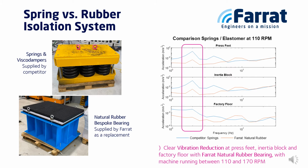Based on this recommendation, the factory went for spring elements and visco dampers as shown in the photo, supplied by one of our competitors. It was reported that the surrounding buildings stopped perceiving vibrations generated by the machine after installation of the product. However, at the same time, it was also observed that the springs, together with the foundation and machine installed with them, started to present unexpected high movement. As a result, premature wear and increased spoilage were caused, reducing the overall productivity of the plant.